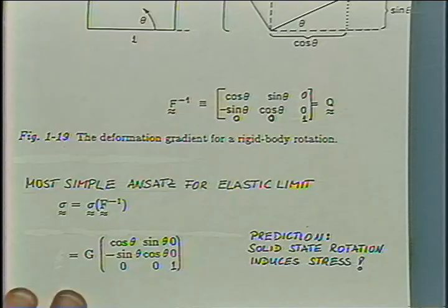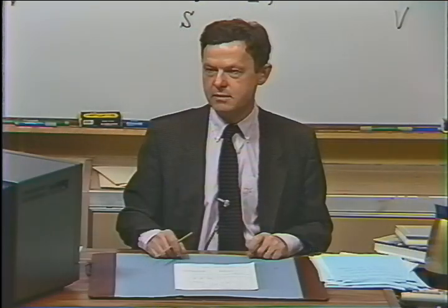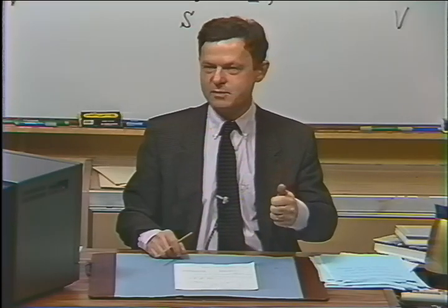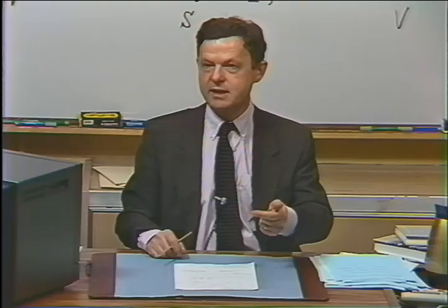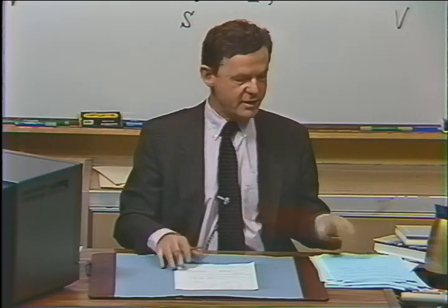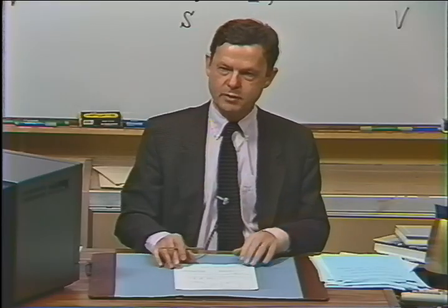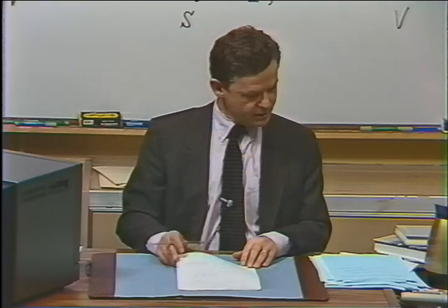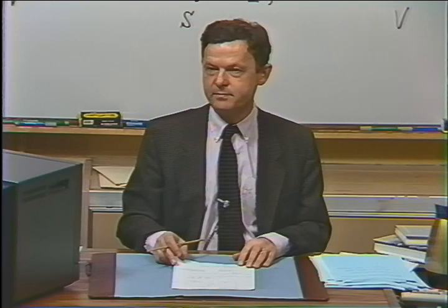So a simple rotation will not introduce any stress in the system. Therefore, the formulation of constitutive equations with the Finger strain tensor or equally with the Cauchy strain tensor is okay. If you just use the deformation gradient, you would violate the third principle here, the principle of frame invariance.